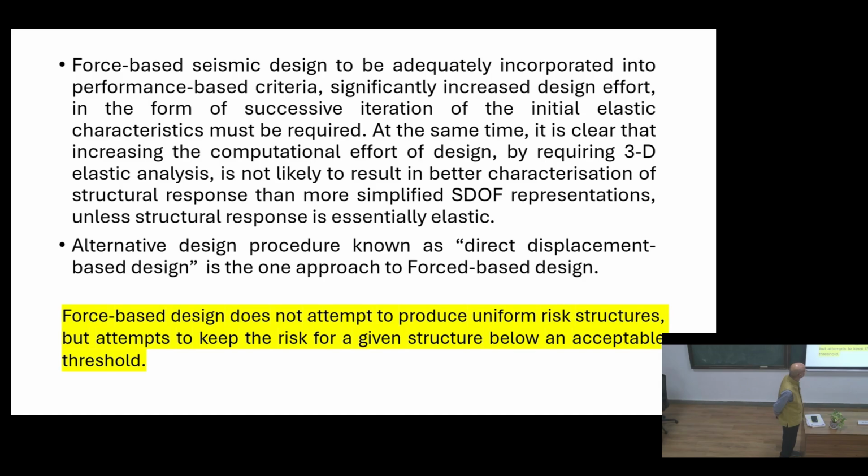Next. So the last line becomes important. Force-based design does not attempt to produce a uniform risk structure, so uniformity is not there. Whereas here you can keep the structure below your threshold limit of acceptance. Whatever you do, in all eventualities the structure performance is going to be the same in similar conditions, which is not targeted in force-based design, whereas in displacement design this is taken care of. That's the advantage of this.